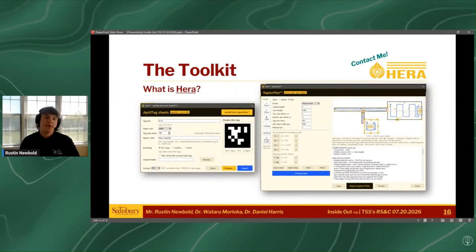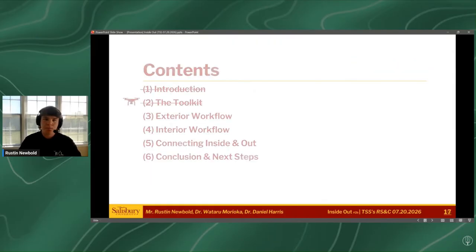Further, there's some cool built-in tools within Hera. One is Capture Plan. Capture Plan is kind of what it sounds like. Basically, depending on what your building layout is, you have these modular components you can throw into the interface, and you can simply snap them together and generate your indoor layout. And it will use some pathing algorithms to actually determine the most optimal path that you should walk, as well as where you should place the AprilTags, the markers, and what type of distance constraints you should have, as well as a built-in AprilTag generator in the software.